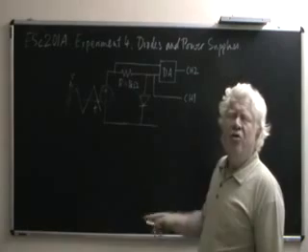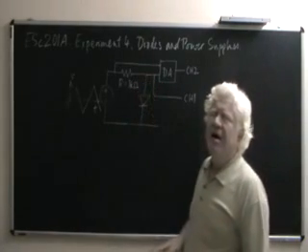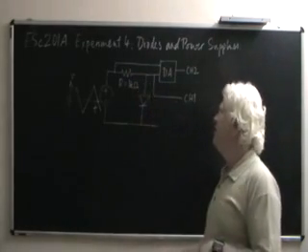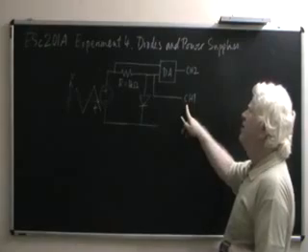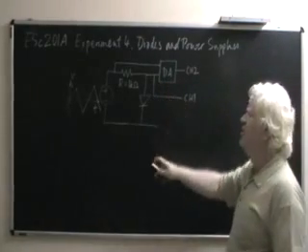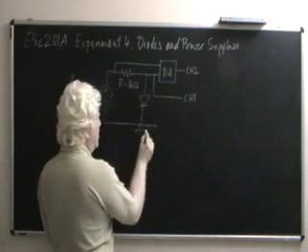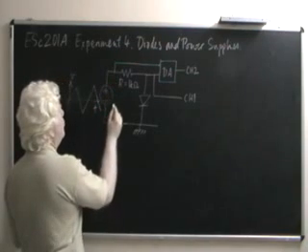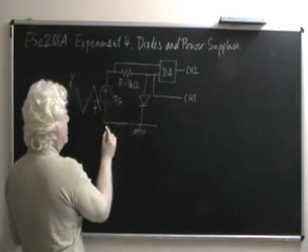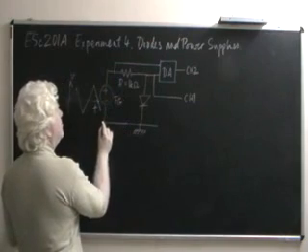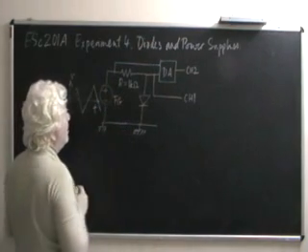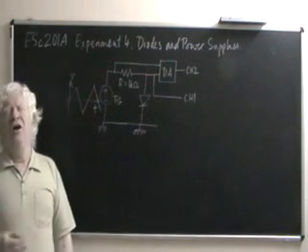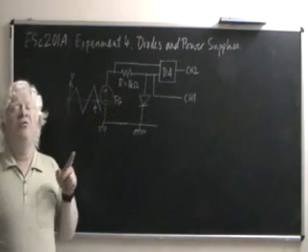are in series. So what the voltage will tell us is a number which is proportional to the current through the diode. At the same time, on channel 1 over here, we can measure the actual voltage between the diode and the ground. This part is grounded because this is the function generator source which produces a supply which is also grounded at one end, and this oscilloscope also makes measurements only of voltages which are with respect to the ground.